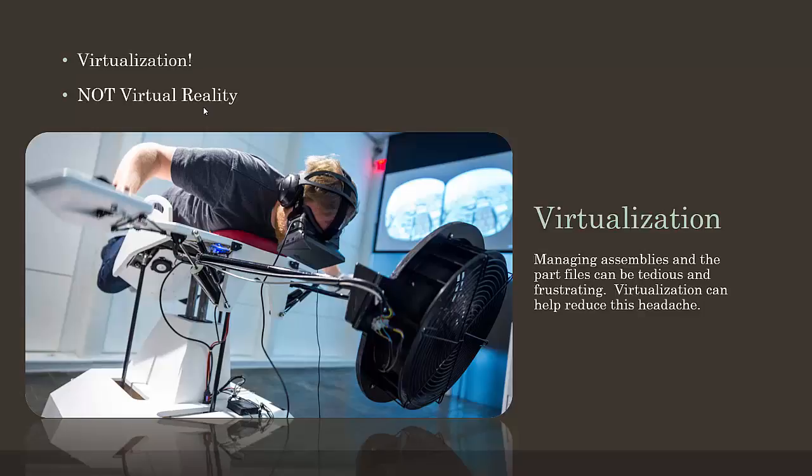So if you zoom into it really close, you'll see that it's very triangulated. It's very ugly. If you use Large Design Review where you can open it up almost instantaneously, that's the same data that you're looking at there. That's why if you go to measuring it, you get the big message saying, look, if you measure, things might be off. That's because you're not dealing with a true circle anywhere. You're dealing with a bunch of triangles, and they're just guessing for you. So that's kind of what you're looking at.